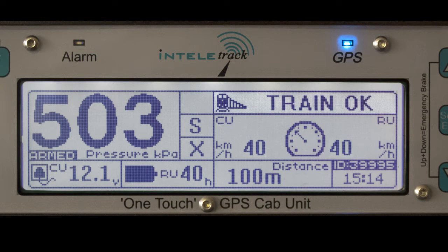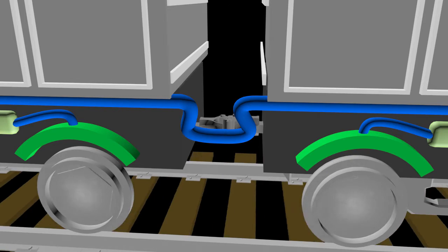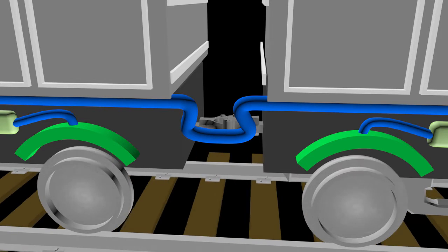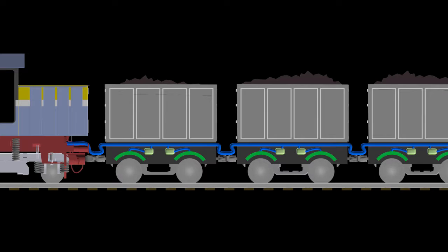This information coming from the EOT, displaying the pressure difference on the HOT in the cab, will inform the driver visually and audibly. The display will confirm if the air brake line has correct air pressure up to the last wagon. This air brake line should be continuous, and it is of utmost importance that the air brake line is uninterrupted, otherwise the train won't handle properly.